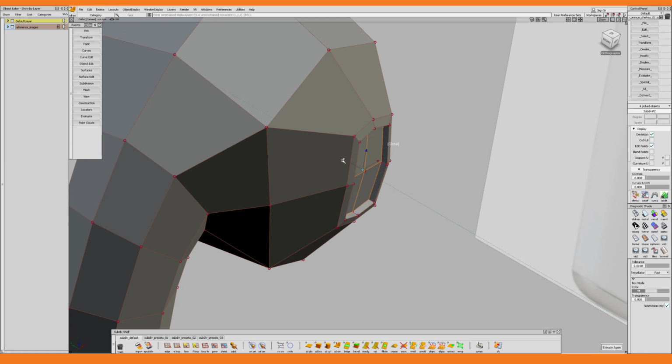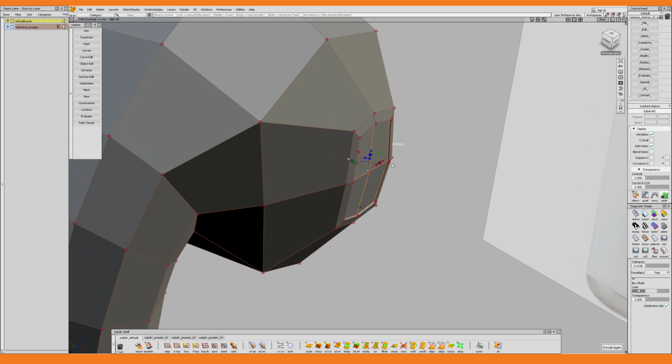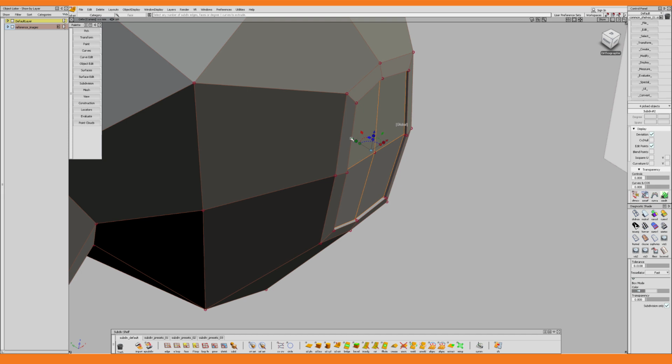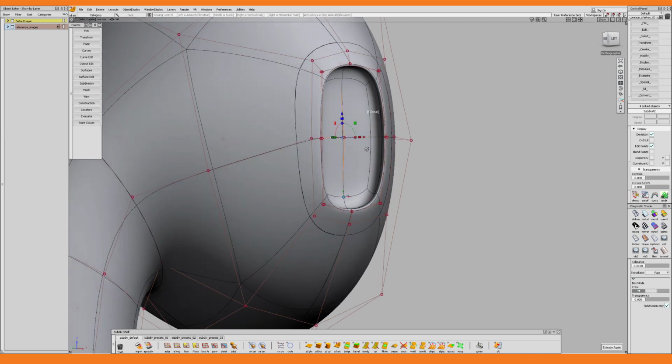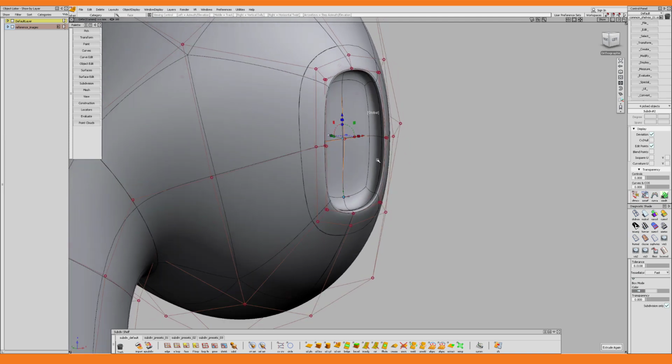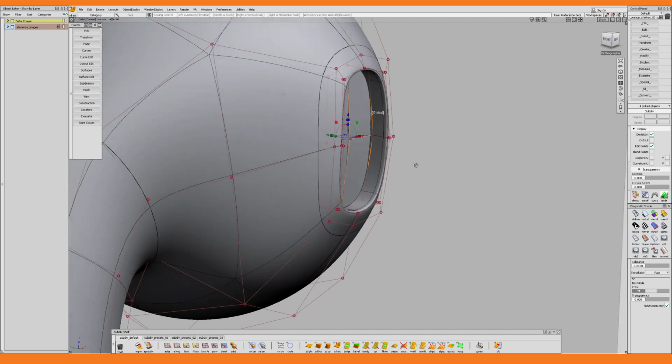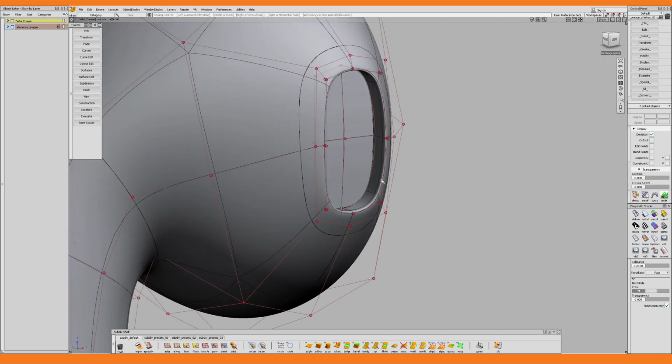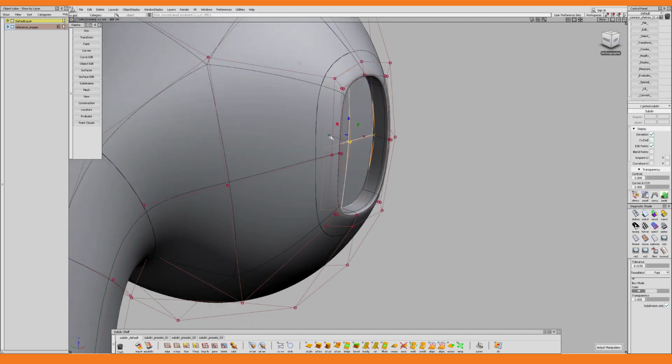Then I create another extrusion, but this time by moving the faces in the y direction. I first make a small one to create a support edge, which will add some definition to the border, and after that I make a bigger one. I don't want a blend between the sidewall and the back surface, so with the 4 faces selected, I click the Extract tool button. With Keep Original off, I click Go, which turns these faces into a separate object, thus removing the blend between